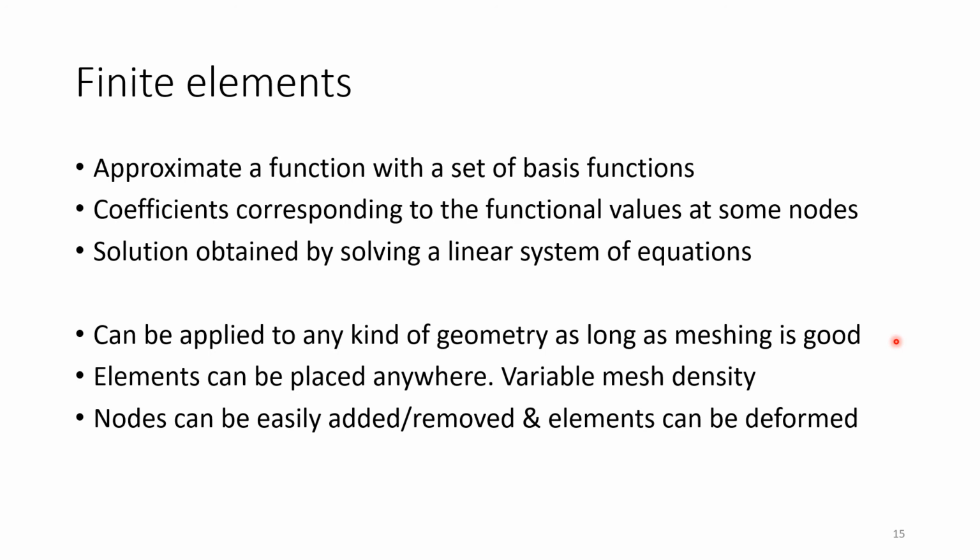Or if you have boreholes, you usually discretize with a high resolution around the boreholes, and the further away you go, the larger your elements become. Right. And as I said, because of unstructured meshes, you can add or remove nodes, you can even deform them. So there are a lot of possibilities, and that's why it's so often applied in numerical simulations, especially engineering applications.